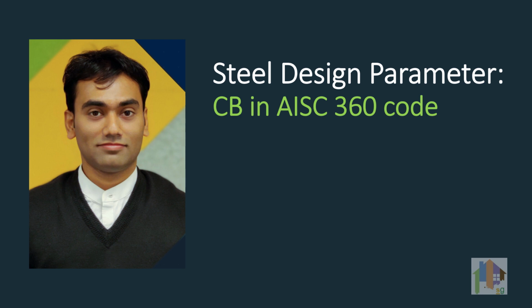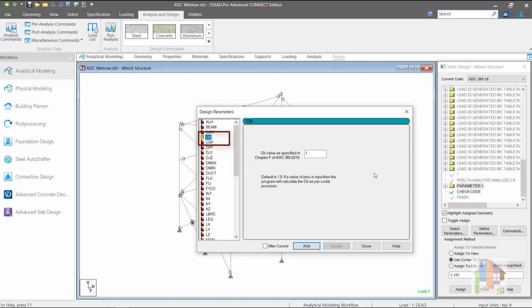Hello everyone, my name is Surajit Ghosh and in this video I will discuss a design parameter that is used in AISC 360 code, the CB parameter. I'll cover how the value is calculated internally, what value to specify depending on different conditions, and how to auto-calculate the value using a custom template file.